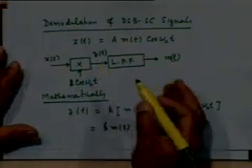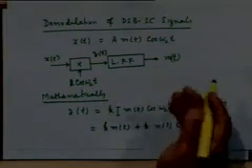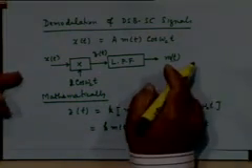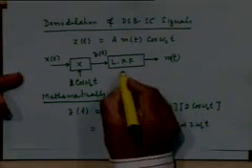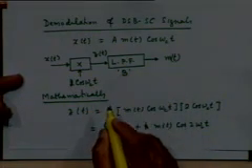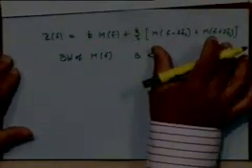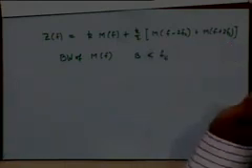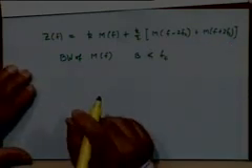The desired signal has a bandwidth of B. You only want the desired signal to appear in the output. So this low pass filter should have a bandwidth of B. And naturally then the components which are centered around 2fc would be eliminated.